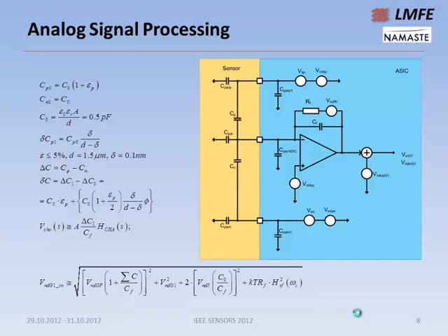I can say that we were able to reach a sensitivity better than 0.1 attofarad. The excitation frequencies for each pair are high frequencies, in terms of, I don't know, 500 kilohertz or something like that. You will see later on the spectrum how it looks.